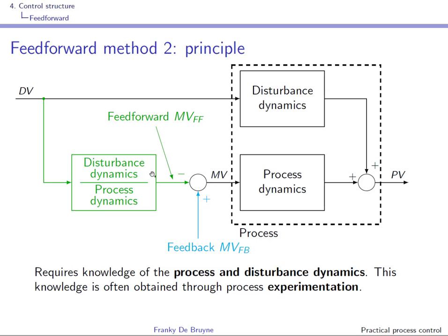Well, as with the first method, feedforward is not going to act alone, so it's always working with a feedback. So this one is coming from a feedback controller. So you have to imagine here a controller PV that comes in the set point, and this one is generating this correction on the feed forward action, right?